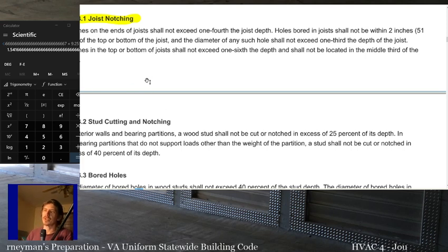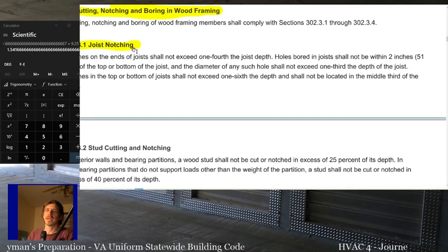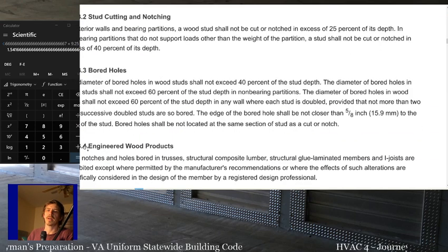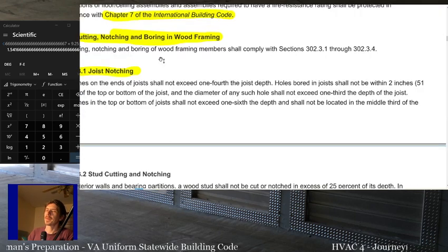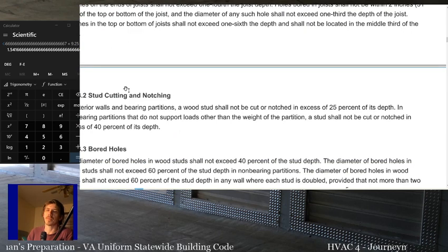And then when you get into bigger buildings, you'll kind of know what pieces are important, like joists or I-beams, and you need to understand that. All right, so that is joists. And just so you know, we're not talking about engineered wood joists. That's a whole separate thing. This is actual 2 by whatever lumber as a joist, not the newer engineered stuff you see in houses these days. That is by manufacturer's instructions.